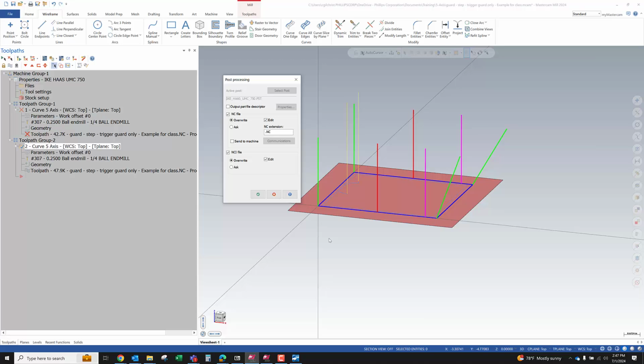And it's important that we ensure that the table is truly flat and level at B-axis 0, and that, as we build up our work holding stack, if, for example, we load a self-centering 5-axis vise on top of the table,